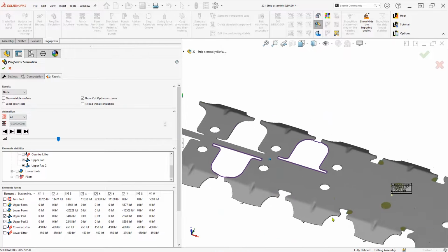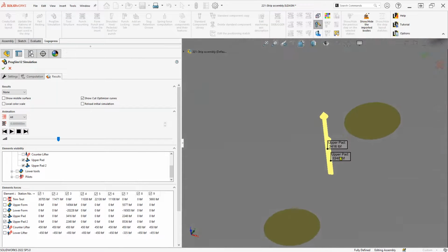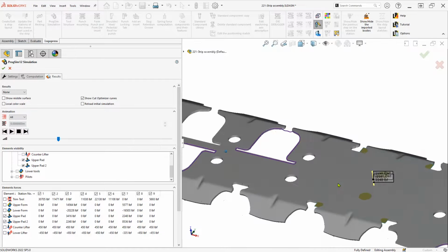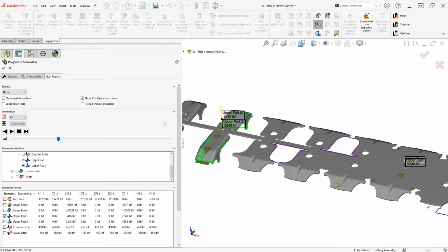And that's not to say that it wouldn't potentially work with something less, but especially when you get into thinner panels, when wrinkling is going to occur. But on something like this, if you had less, it wouldn't stay perfectly flat. It would start bowing the part up, that top portion of the part. When AutoForm sees that the part starts to move, it keeps pushing down until it doesn't move anymore. Is that a correct way of saying it, Paul? Yep, that's correct. Okay.